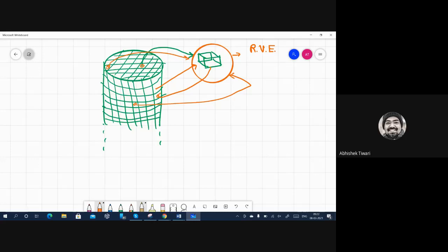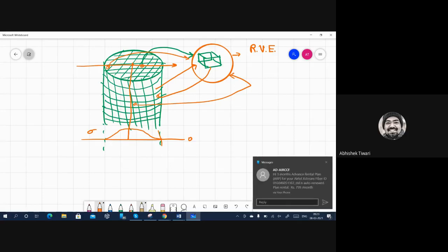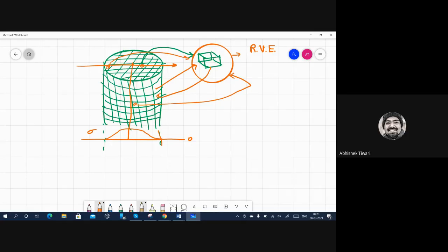So let us have a look at the situation which might alter if we change the position. At the center, if you go across the specimen, you will have high constraint. Because of high constraint, you will have high stresses. At the surface, usually the stress is zero. As you go toward the center, the stress increases, and at the very center, the stress will be maximum.